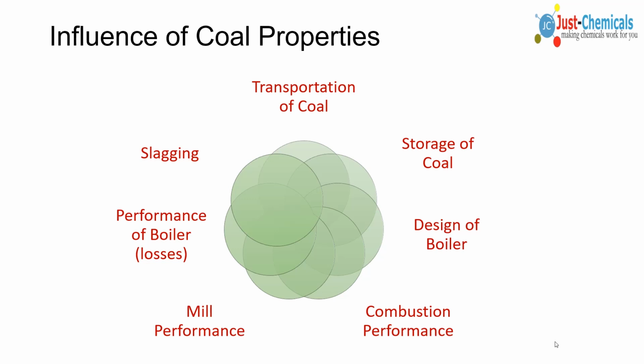Then storage of coal, yes, that is also influenced by properties like volatile matter. If the volatile matter is high during the storage of coal, you will have spontaneous combustion. And also moisture loss would be there as an air drying effect will happen on the top of the coal. At least 6 to 7 inches of the coal on the top will dry up.